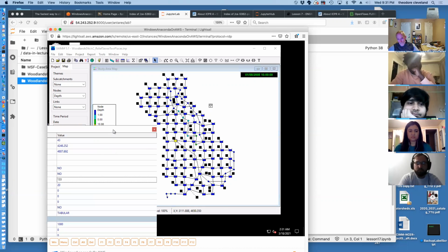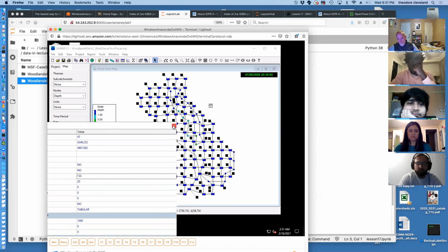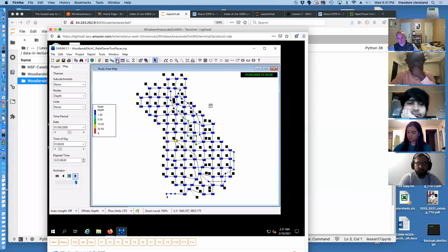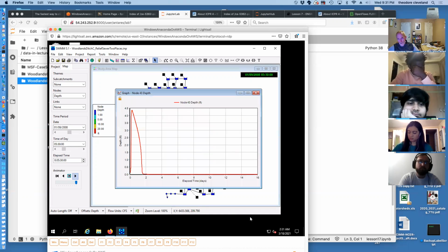Now we might not be super happy because 4.5 feet deep in a subdivision cell, where anything above a foot we consider flooding, and maybe at 1.5 feet we're actually getting to the finished floor elevations of the residences. So that's going to put 3 feet of water in their houses. They're going to be unhappy.